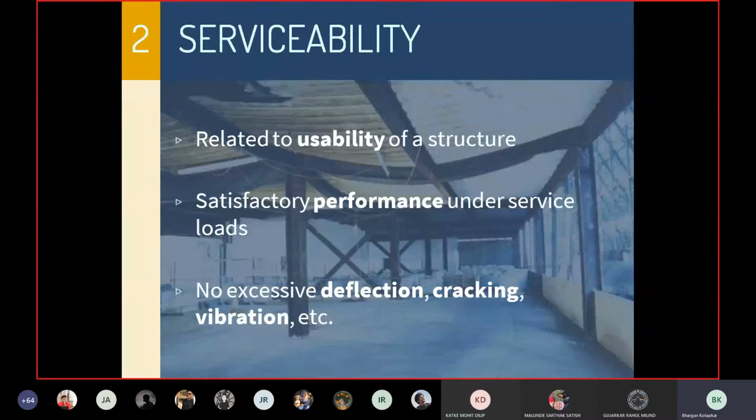So everything depends upon the duration of the fire. If the fire is about 2 to 4 hours, concrete may sustain it, or be able to resist this fire. But if it's a very long fire, 7, 8, 10, 12 hours, then ultimately the reinforcement within the concrete is going to give up, and the column as a member is going to give up. Naturally the steel embedded in that concrete is going to be subjected to the fire, and ultimately it is going to give up. So it all depends on the duration of the fire.